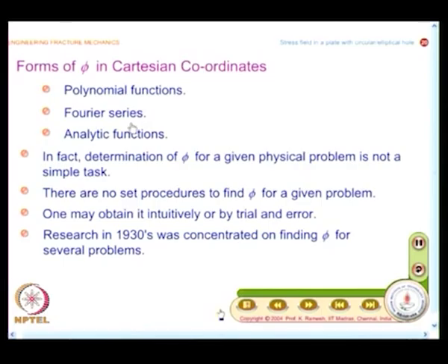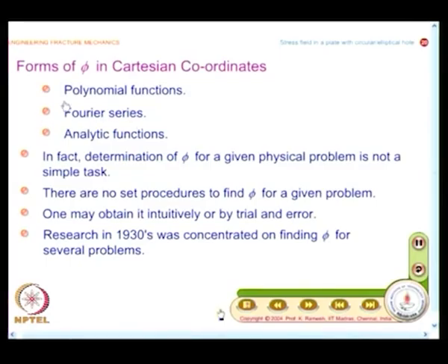See, in fact, when you are learning a first level course, you learn the bending moment diagram and shear force diagram to understand how the bending moment changes along the length of the beam. You normally take up concentrated loads, because they are easy to illustrate how a bending moment could be drawn. When you come to theory of elasticity, it is always convenient to handle a distributed loading. Concentrated loads are difficult to handle. So, when I have a concentrated load, I have to use a Fourier series and invoke several harmonics to obtain a concentrated load. So, you will find the solution to 3-point bending is done in a much more complex fashion using Fourier series than a beam with a distributed loading. You learn it the other way when you are learning the bending moments.